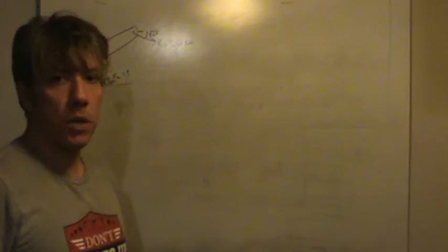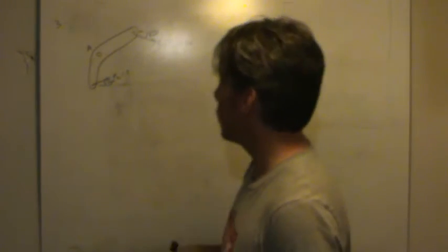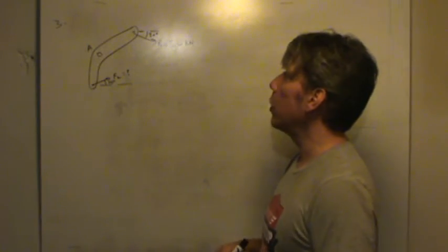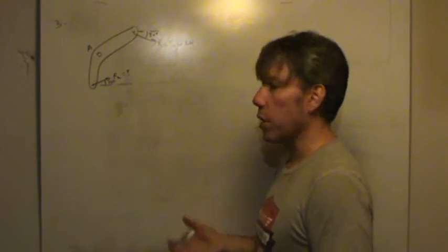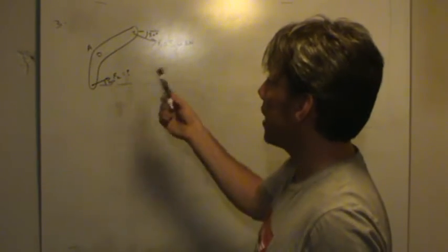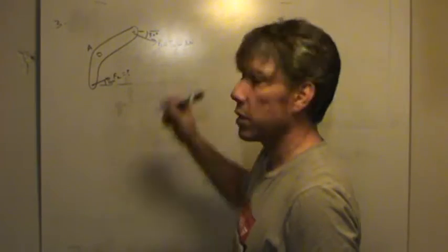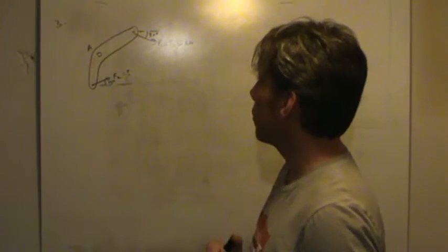Now, I don't think that this is something that's going to rotate and accelerate very fast, so I don't think that there's much dynamic loading to be considered here. This is not a terribly large piece if you look at the overall dimensions. The dimensions are all on the order of tens of millimeters, so definitely less than 100 millimeters is not all that big. So I don't think there are any dynamic considerations going on here, and we can calculate F2 based on statics, and that should be close enough for what we're doing.